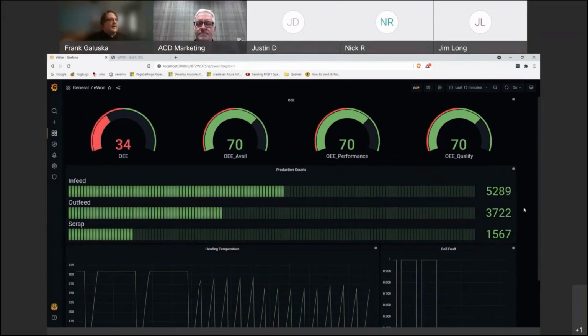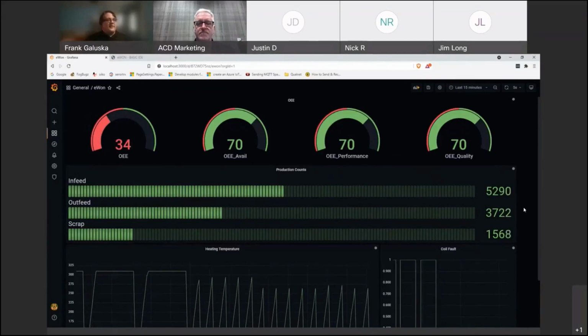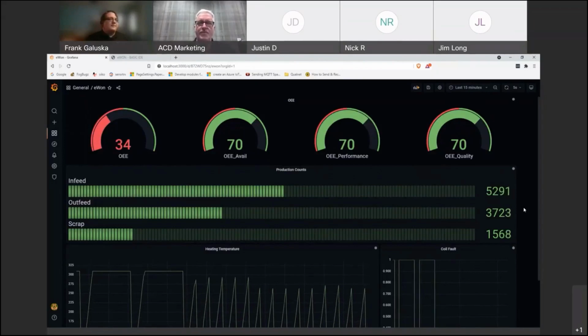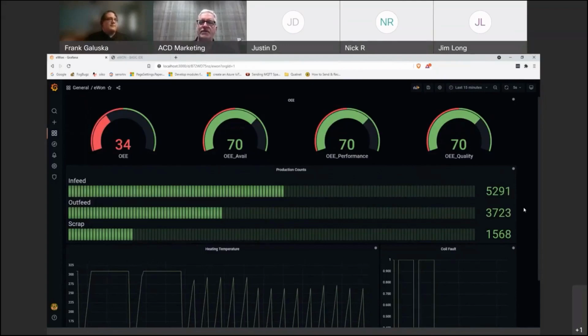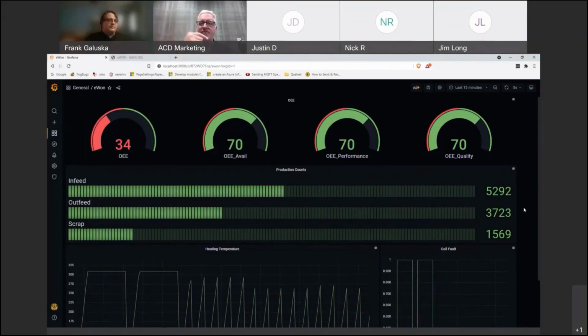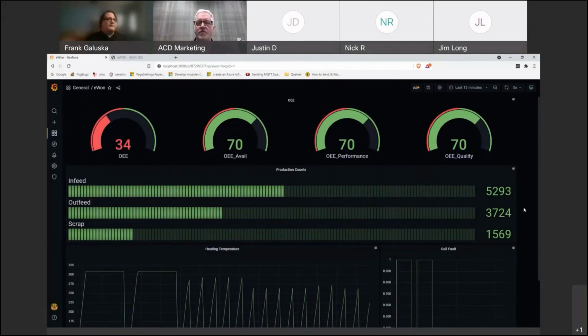Awesome. And one other thing to note, like we talked about last week, is that this is report by exception, so it's only when this data is changing that it sends those topics out. Yep, it's one of those rules: report by exception. Data goes one direction, and it's only reported when it changes, which saves significantly on bandwidth and makes security better, because protocols like OPC UA are bidirectional request-response. You don't have to open up the firewall, if there is one, to allow the request to go through. It's just coming through one way on the way out.